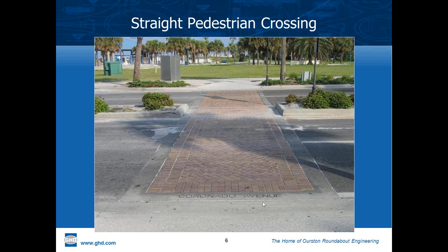You would think that you want to provide, you know, ample gaps for pedestrians, but because the pedestrian volumes are so high, it impacts the roadway capacity because they just cross indiscriminately. So they've had to control the pedestrian flow using signals. That's a common concern in London, England, and places where there are roundabouts with very high pedestrian volumes, is to use the crossing signals as a metering device.